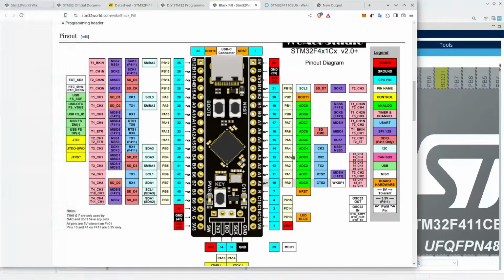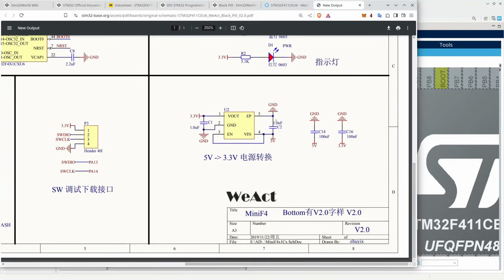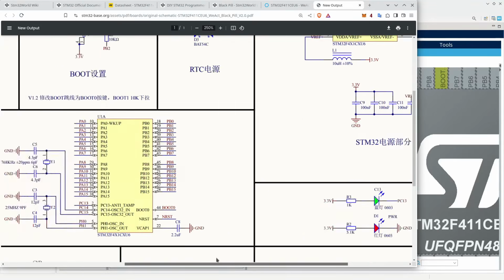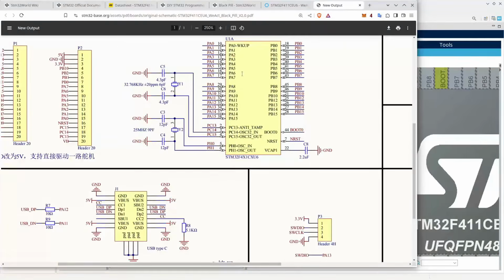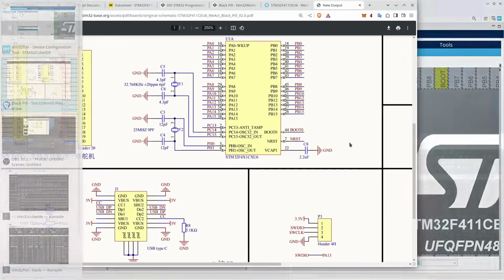And again, let's look at the schematics for this board, which we have here, the MCU, and you will see PH0, pin 3 and pin 6 are running to the crystal. Let's look over here. That is pin 5. Oh, pin 5 and 6.